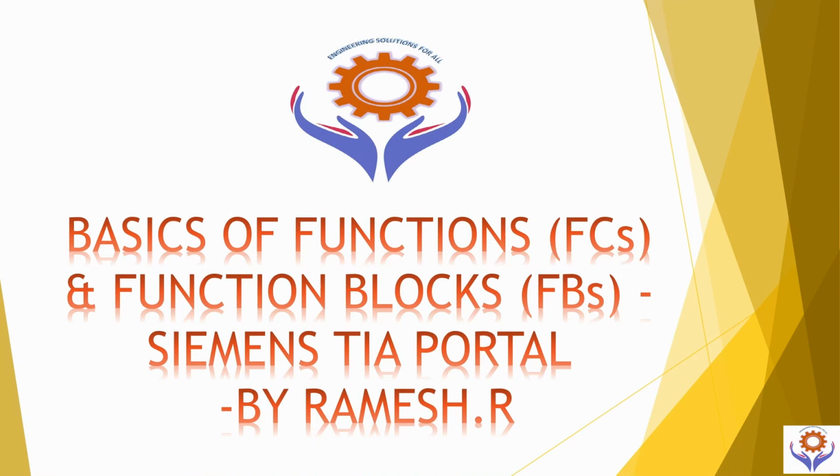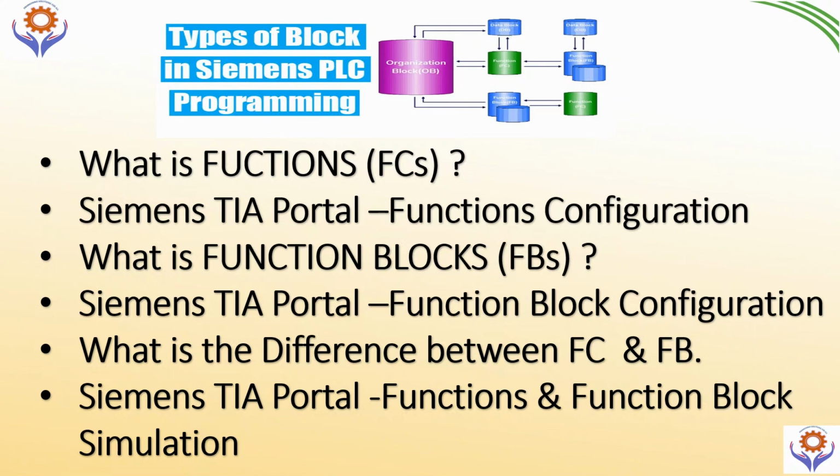Today we will see the basics of functions and function blocks by using Siemens TIA Portal. In this video, we will cover topics such as what functions are and function configuration using Siemens TIA Portal, what function blocks are, function block configuration using TIA Portal, and the difference between functions and function blocks. Finally, we will see the Siemens TIA Portal simulation by using functions and function blocks.